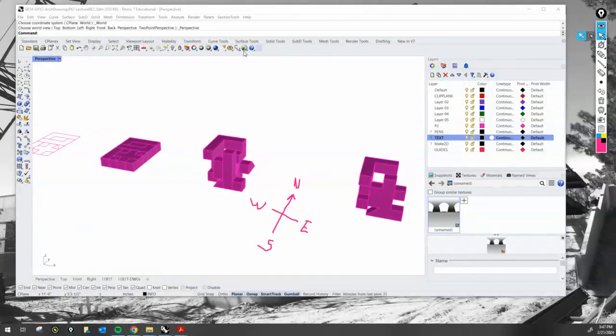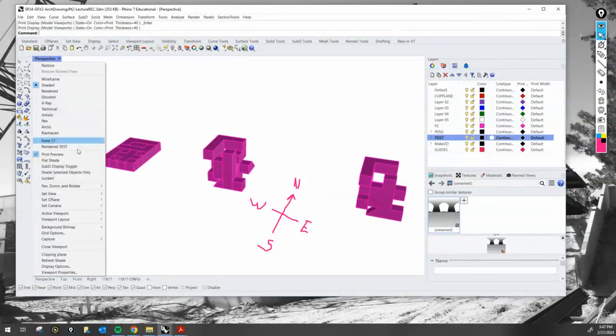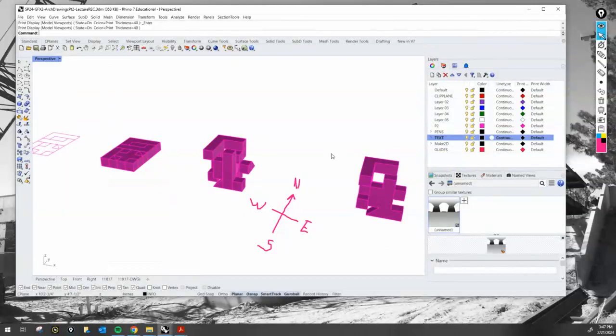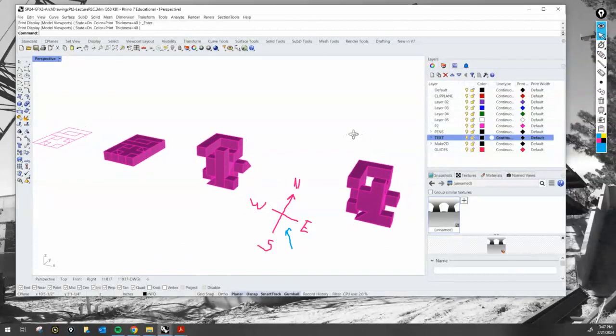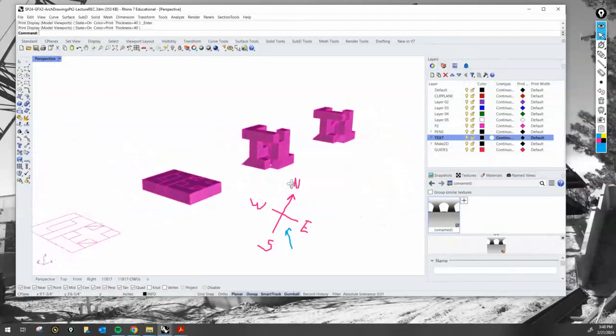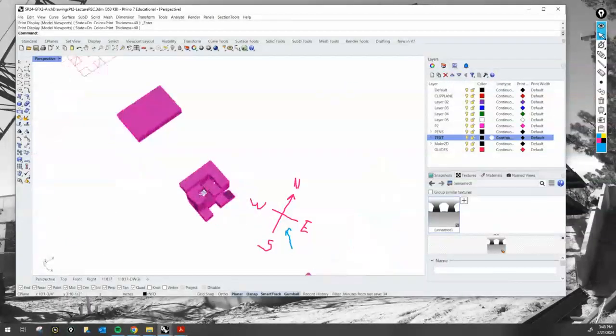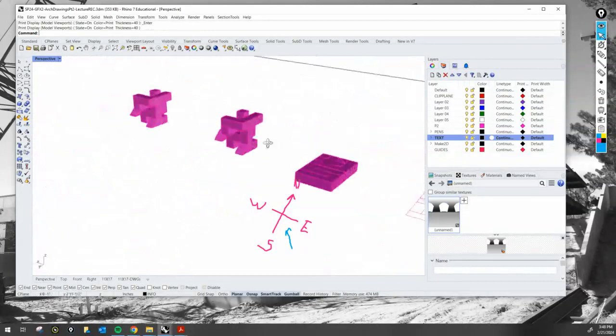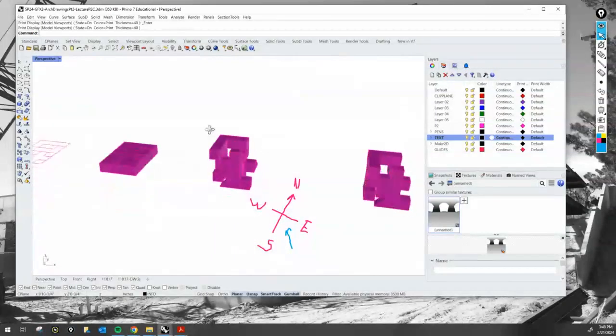You see that on these isometric views, Set View Isometric, they're defined by a combination of these two: northeast, northwest, southeast, southwest, and that's what that stands for. So southeast would give you this view, a little like what I have right now. That would be your southeast. This would be your southwest. This would be your northeast. This would be your northwest.